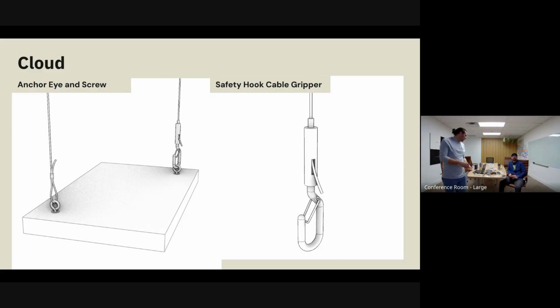And then the two ways you can do it is they can just use aircraft cable in a loop with a ferrule, or they can use a grip locker that has a hook on it. And it has the same little plunger, all the great things about our grip lockers. It just has now this locking hook that snaps in, gives you easy adjustability. If you have to remove them for some reason, super easy this way.